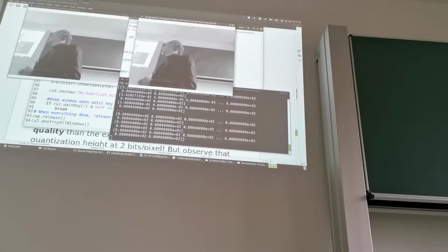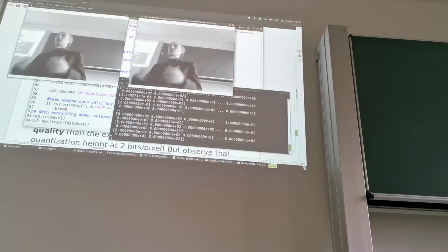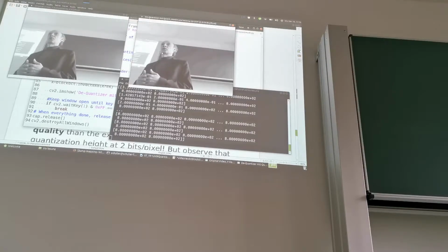And this gives us indeed a big boost in image quality. Now we don't need so much quality anymore to recognize what's going on. It contains much more visible detail in this case. This should show you that it's really worthwhile to do the quantization according to the contrast sensitivity function. It gives you information about what the eye is looking for.